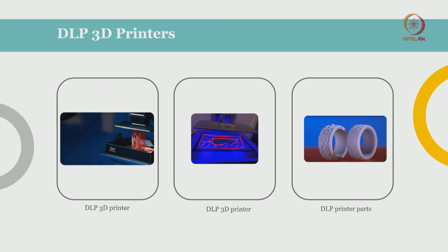Just after that you can see an image of a jewelry, which is actually not jewelry, it's a printed part, mostly made of wax material. You can place this kind of highly complicated ring design in molding sand, pour molten gold or silver or whatever you want, and get a golden or silver jewelry exactly like this. This is the major use of DLP printers, because they are much more cost efficient than SLA printers. This is the main advantage of DLP printers.